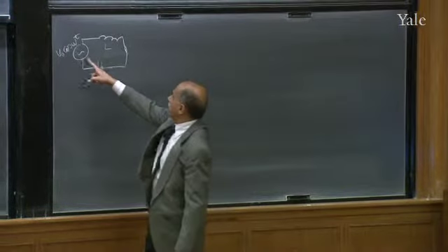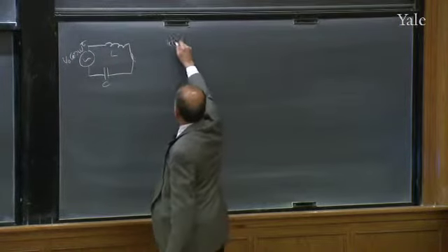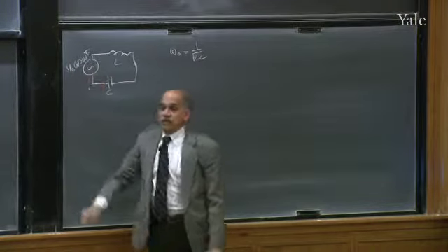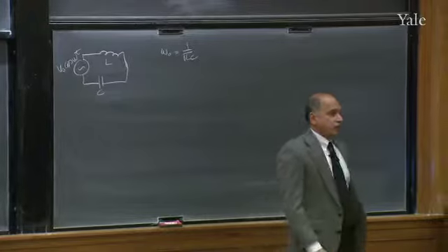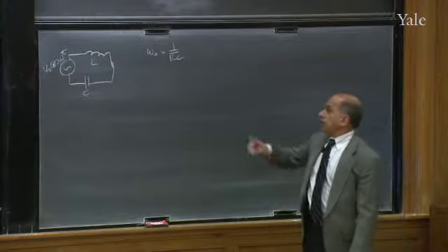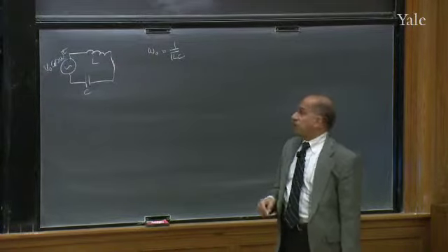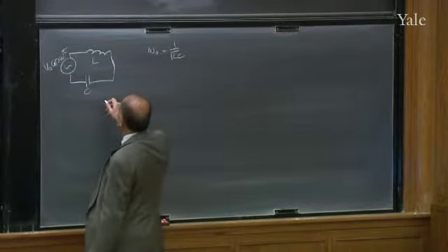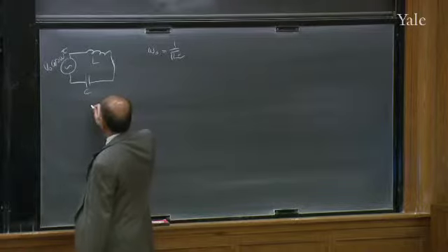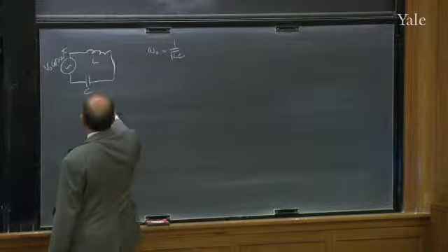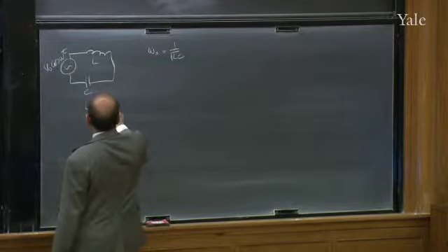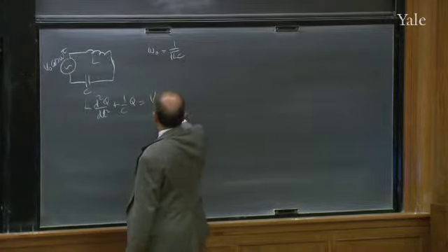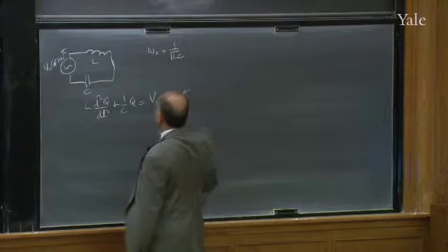This omega is not the natural frequency of oscillation. It is some externally given omega, like 60 hertz from your power supply, from your socket. So that's driving the circuit. And you can ask, what happens now? The answer will be, you write the same equation. You can write L d2q over dt squared plus 1 over C q is equal to V0 cosine omega t.